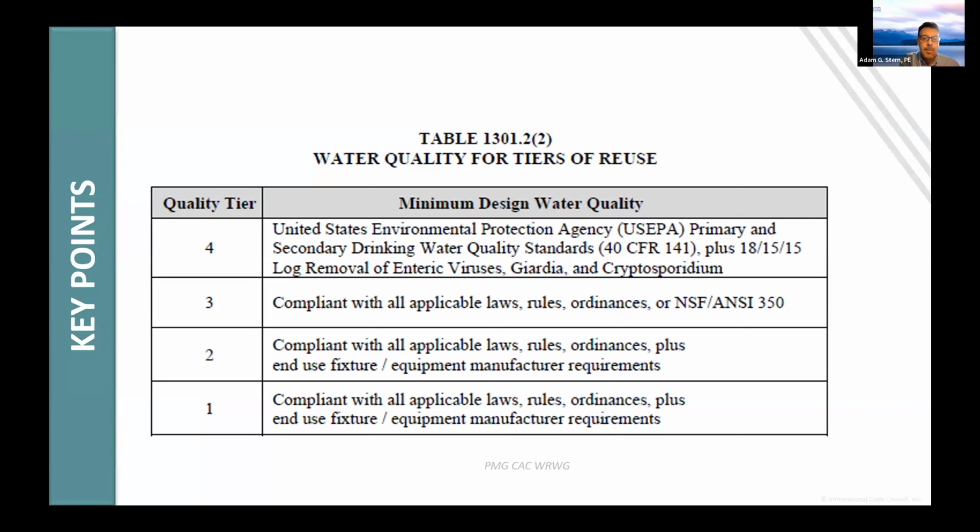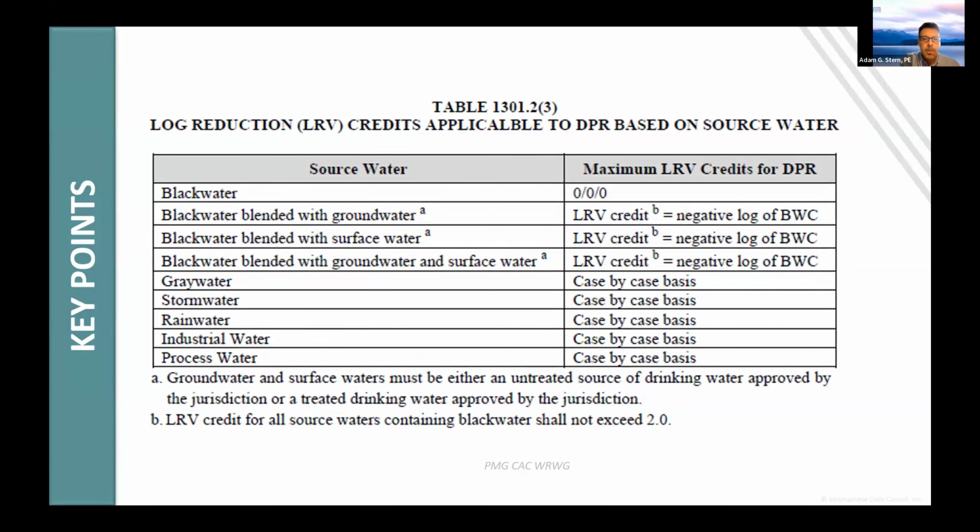So in addition to meeting the standards of the Safe Drinking Water Act, we've layered on log reductions. Log reductions, I assume everyone is familiar with, but if we talk about 3 log reduction, that means 3 nines, 99.9% reduction. If we talk about 8 log reduction, that's 6 more nines. So we came up with also several different tiers, and Rich, I'm catching up to here. So again, we're trying to set minimum standards, but also be flexible.